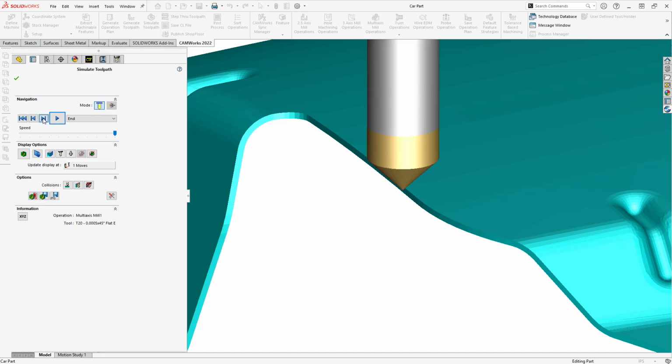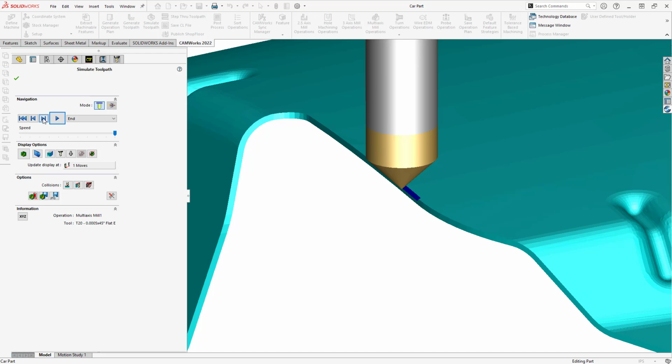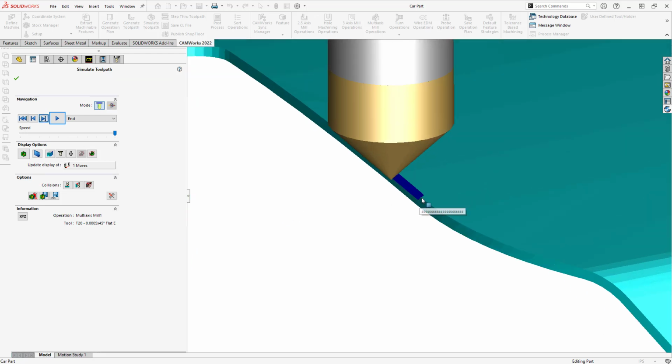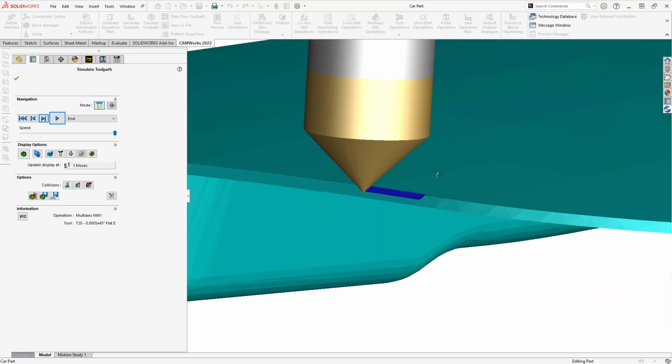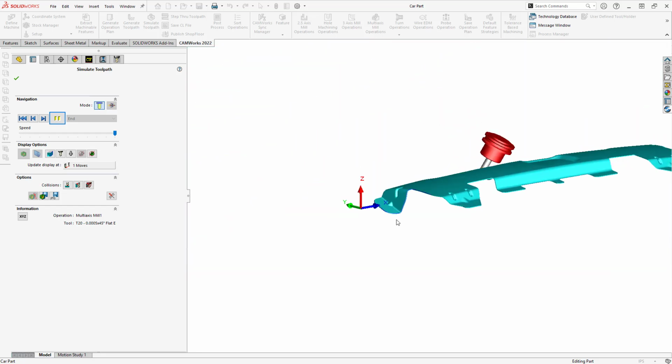So the tool comes down from that retraction plane. It's into position, lead in, and there's our first cut. You can see it's going in the climb direction. If I run this for just a little bit here, what we're going to get is trimming of the entire part. And you can see there's some tilting going on there as well.